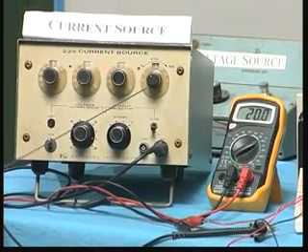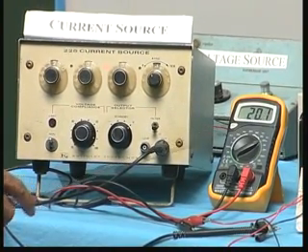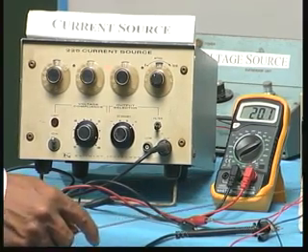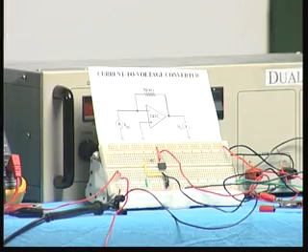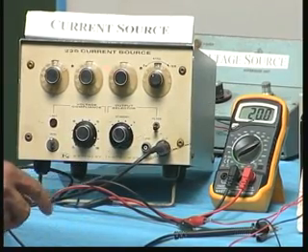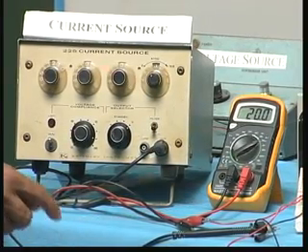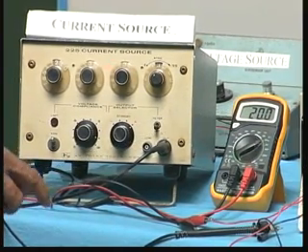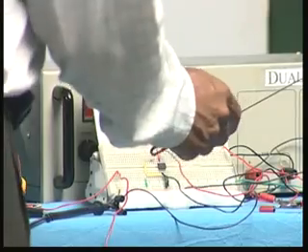You are applying 20 microamperes and you are also reading 20 microamperes in the multimeter, and that is being applied here. You have a 10k resistor, so multiply 20 microampere by 10k, that will be 200 millivolts. The k and the micro will make it milli. So 200 millivolts should be the value of the voltage.